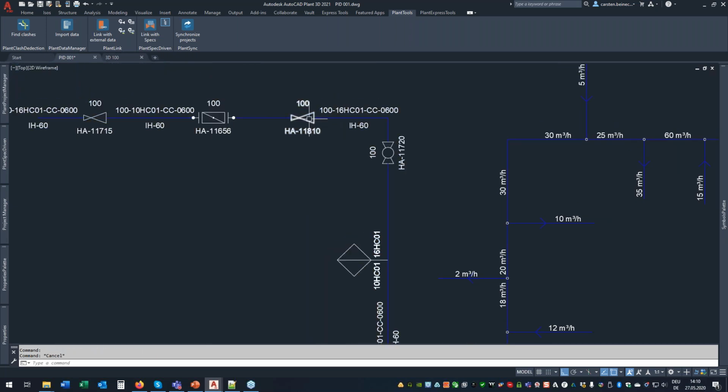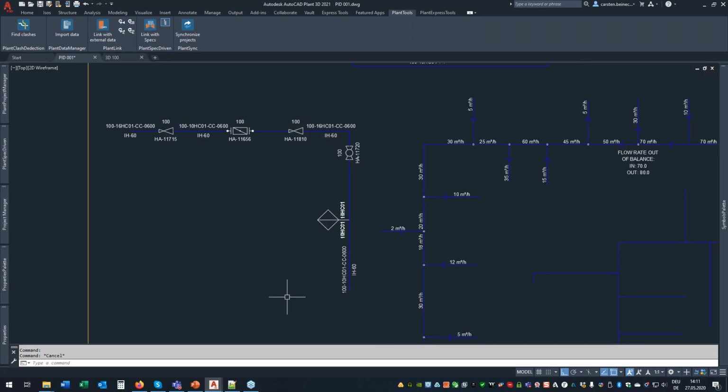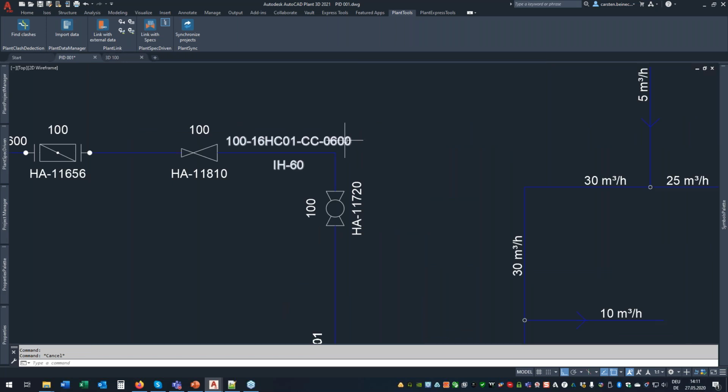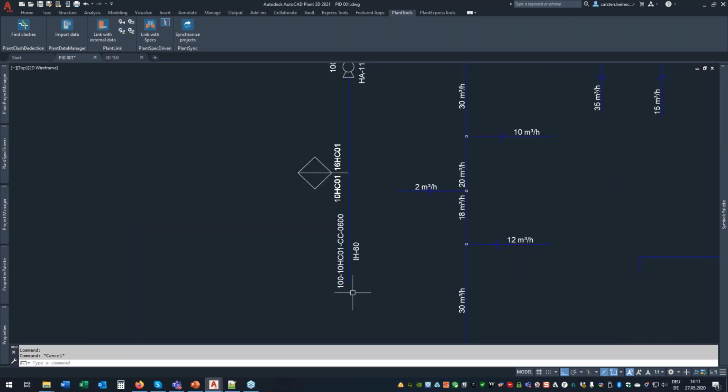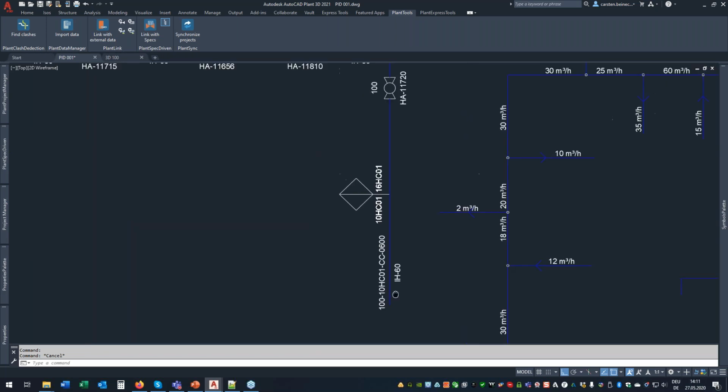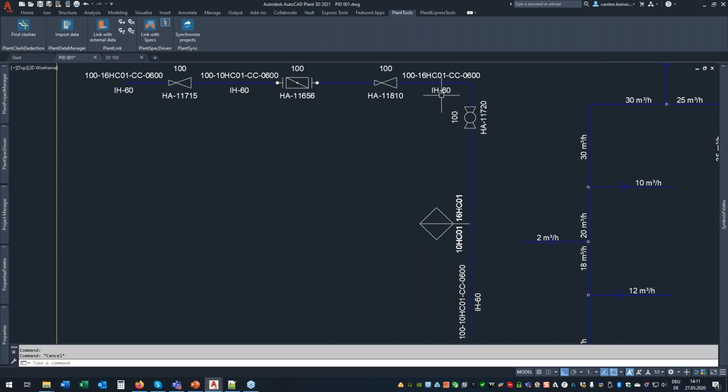This is a pressure reducing valve, so there is a segment stopping here, then I have another. So I have multiple segments within one pipeline group, number 600. In my case, the way I configured it, let me just put this on. So you see the insulation here in the annotation everywhere. So if I change